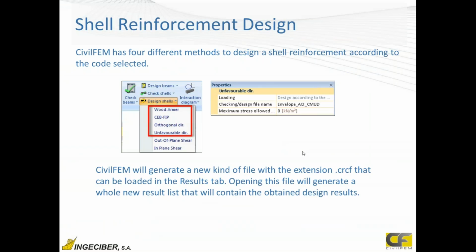We can perform the design for the slabs and for the beams. And then the process will be, after performing the design of reinforcement of each load combination, to perform an envelope, so we can get the maximum values of the design reinforcement.